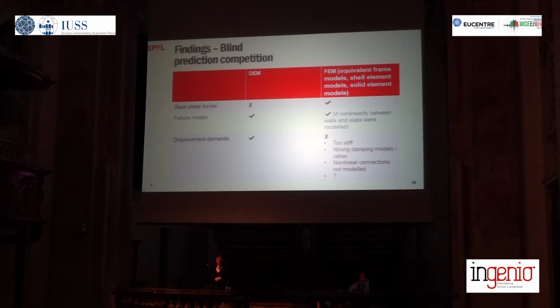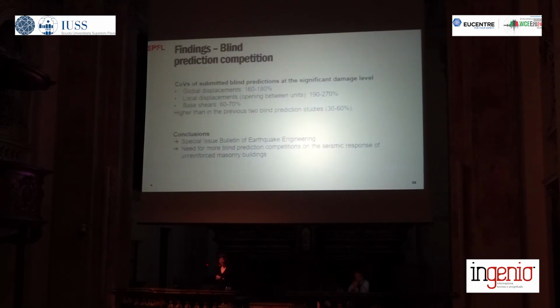For us, wrong damping models. I think some others used wrong damping ratios, or not very good estimates of the damping ratios. Another problem in other finite element models was that the nonlinear connections between diaphragms and walls were not modeled. If they were not modeled properly, we also saw that the failure modes were not captured very well.